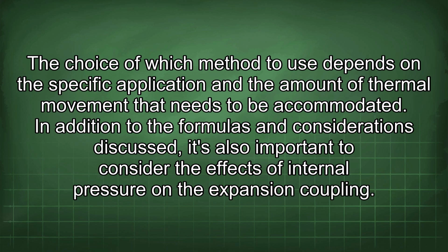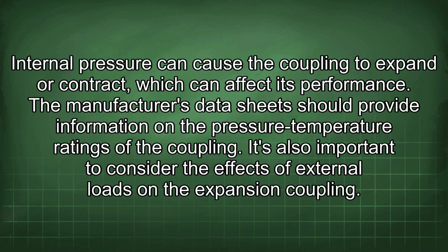to be accommodated. In addition to the formulas and considerations discussed, it's also important to consider the effects of internal pressure on the expansion coupling. Internal pressure can cause the coupling to expand or contract, which can affect its performance. The manufacturer's datasheet should provide information on the pressure-temperature ratings of the coupling.